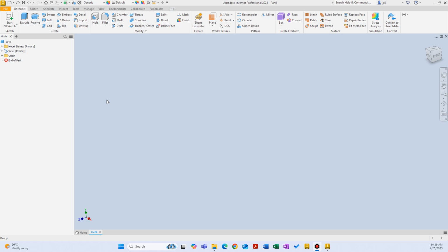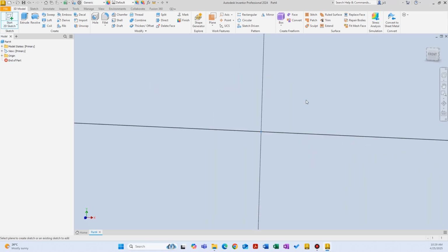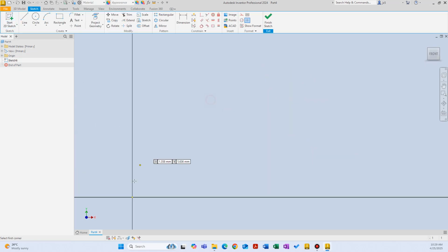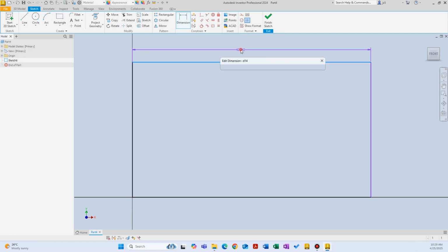It's commonly used to modify the 3D object. We talked about it a little bit, but now in this video we're going to talk about it in a little bit more detail. And before we create our sketch, notice that your extrude option here is on the left, and you have right next to start 2D sketch. So let's start a 2D sketch on XY plane, and let's draw a 2-point rectangle starting from the origin point, and let's assign some dimensions to it.